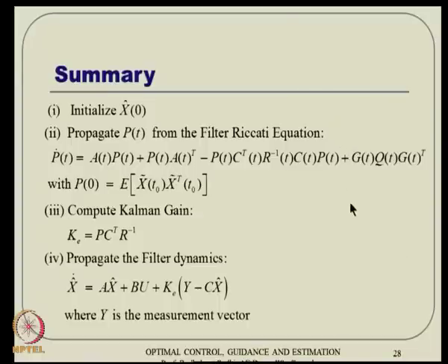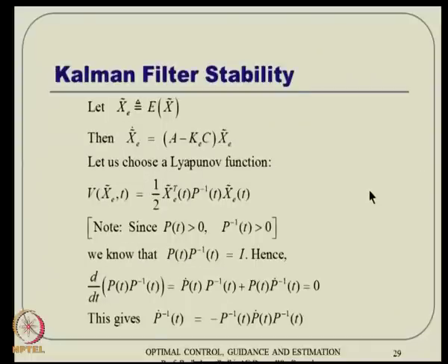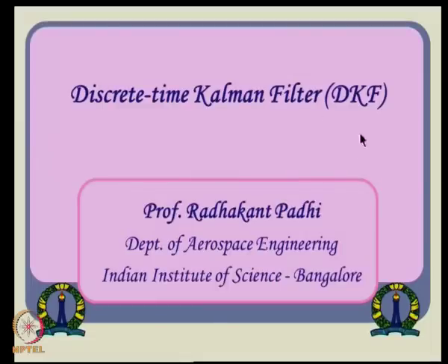But as I was talking some time back, what we are interested in is a framework where we can incorporate a discrete measurement equation. So, that leads to the concept of the discrete time Kalman filter. In other words, the system dynamics can be continuous, though it is not typically continuous, but we can mathematically discretize it, whereas sensor outputs are typically discrete and we can't make them continuous. It may not be feasible because the sampling rate may not be sufficiently fast to interpret it that way. So, let us see how we can derive everything in discrete time.